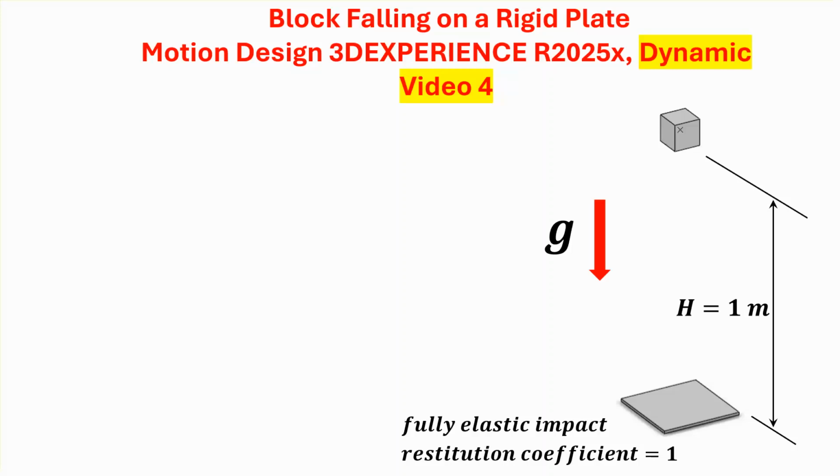So we have a block that is falling from a height that's shown here under gravity, and it is going to hit the block and basically bounces back or it sticks to it, depending on a few other things that we're going to talk about. In this particular video, I'm going to assume that it's a fully elastic impact. In other words, when it hits the plate down there, it bounces back without essentially losing any energy. Therefore, the coefficient of restitution in a problem like that is actually 1.